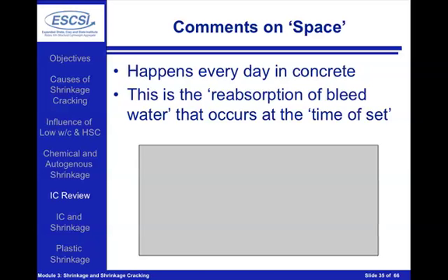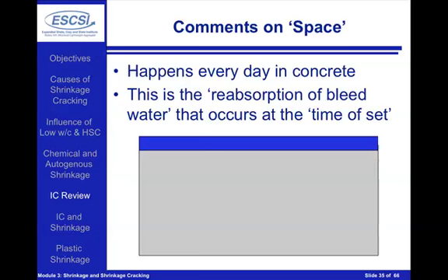Now you may say all this sounds like something I don't see in my normal concrete, but I want to take a step back and say that this happens every single day inside of concrete. Many people notice that bleed water can come to the surface of concrete. Well, actually what's happening is all the other particles are sinking down, and it's really the water that's not sinking as fast as everything else, and that's forming the sheen on the top surface. Now the interesting part of this is we know that when the water sheen goes away, this is really correlated to the time that the concrete starts to set.